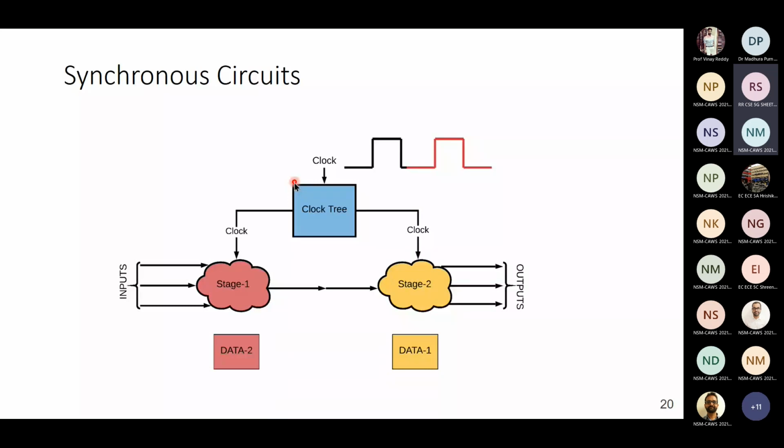Now, before I start talking about this, I want to mention one or two important aspects about ASIC design. When we start designing something like a processor, I think yesterday you had a lab on RISC-V implementation, right? As you all know, if you have to design RISC-V, you have to use something like SystemVerilog or Verilog, where your ASICs are going to be synthesized for a given technology node. And then you will have a separate set of tools which will allow you to simulate and check whether your circuits are actually working fine.